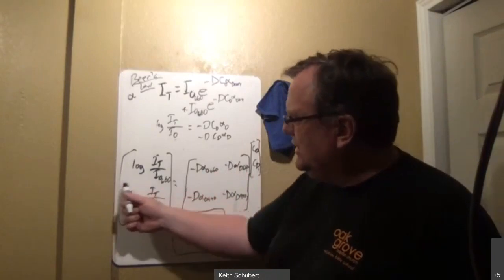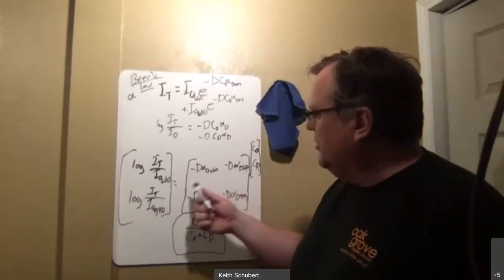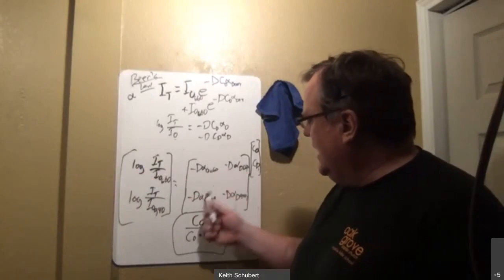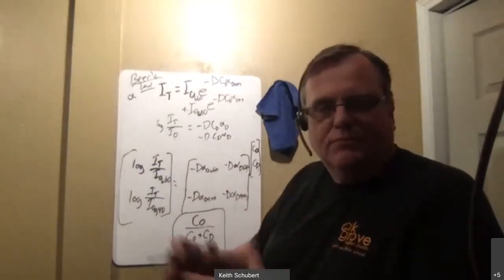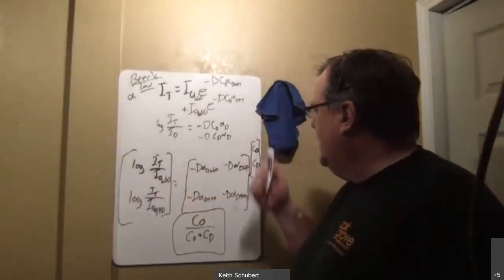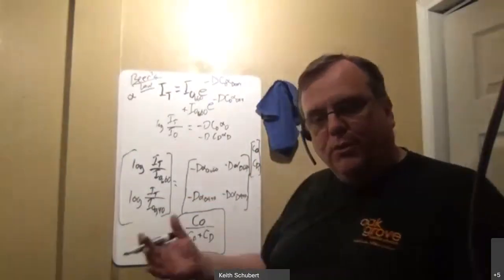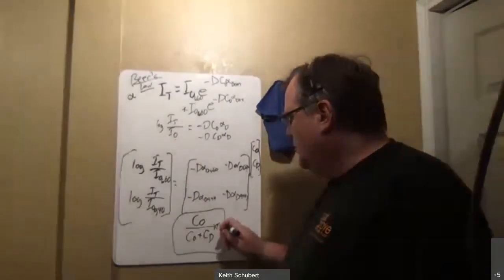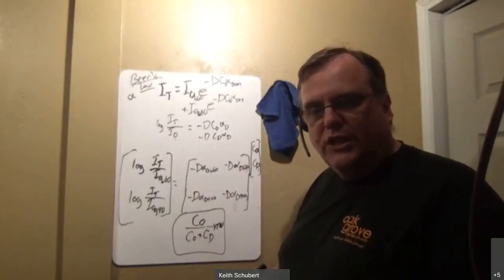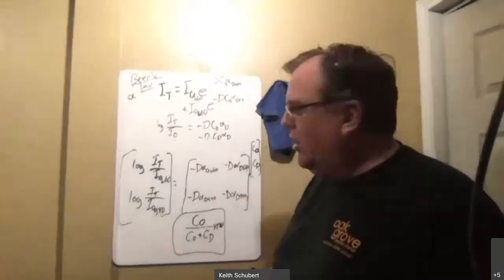And that's why I said sometimes you see the D over there, sometimes you see it over here. I could pull the D out of here if I wanted, and I could scale this side. Or I could do 1 over D, and then all my measured values are here. And then the alphas are taken from a table in advance. And so I just invert that, multiply, and I would get my values of C_O and C_D, stick it in this ratio, and boom, I've got my oxygen. Multiplied by 100, and now you've got a measurement of the percentage. And that works really awesome as long as all of these values are straight on.